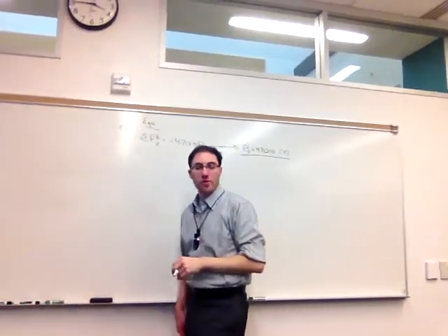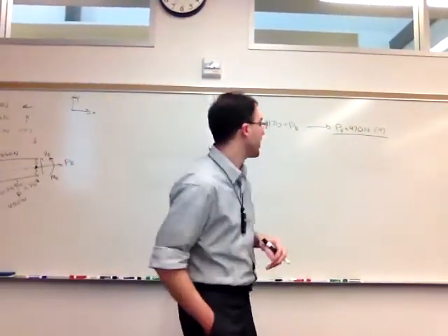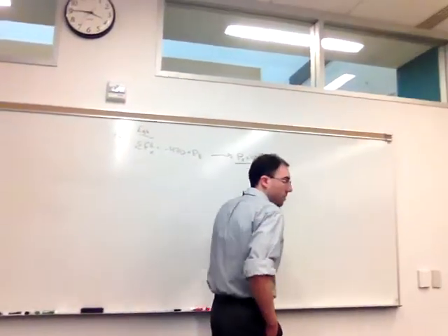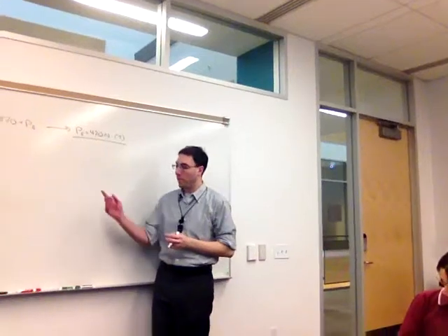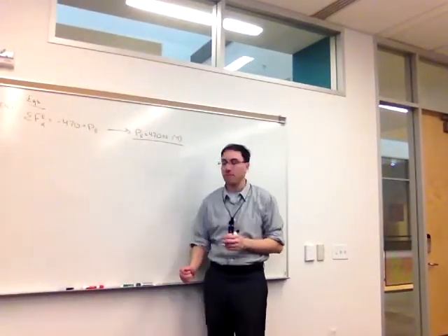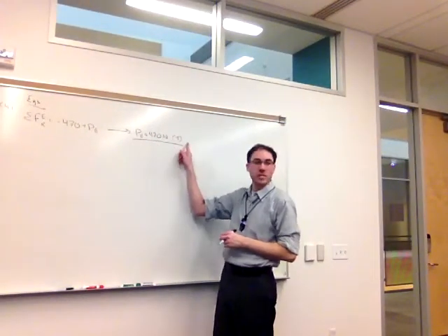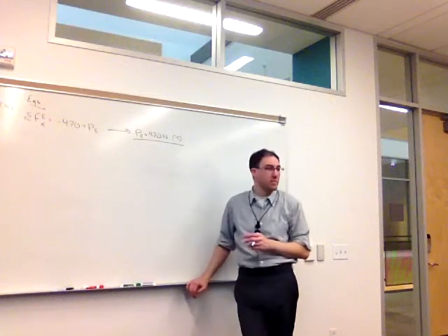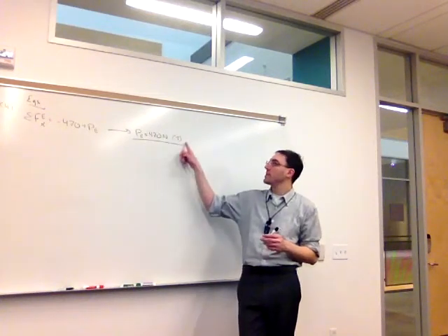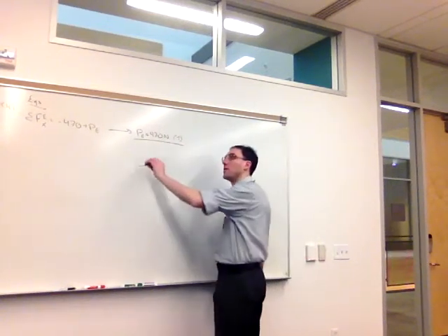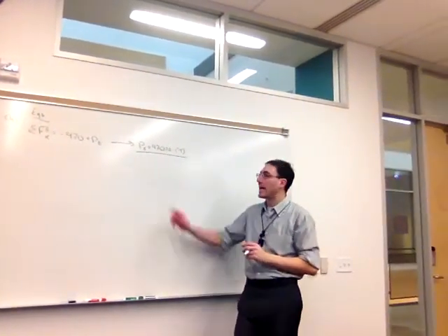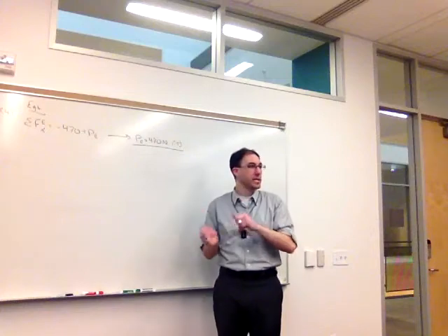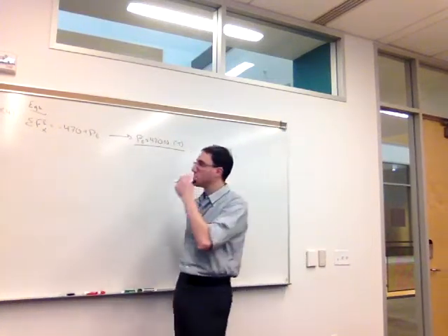At point E, the internal normal force is 470 newtons. Internal normal forces we can interpret as being tension or compression. So by our assumption of coming out from the surface of the cut, a positive will always mean tension, a negative will always mean compression. We don't have this same interpretation for the shear force, or for the bending moment. It's just the normal force that can be in tension or compression.